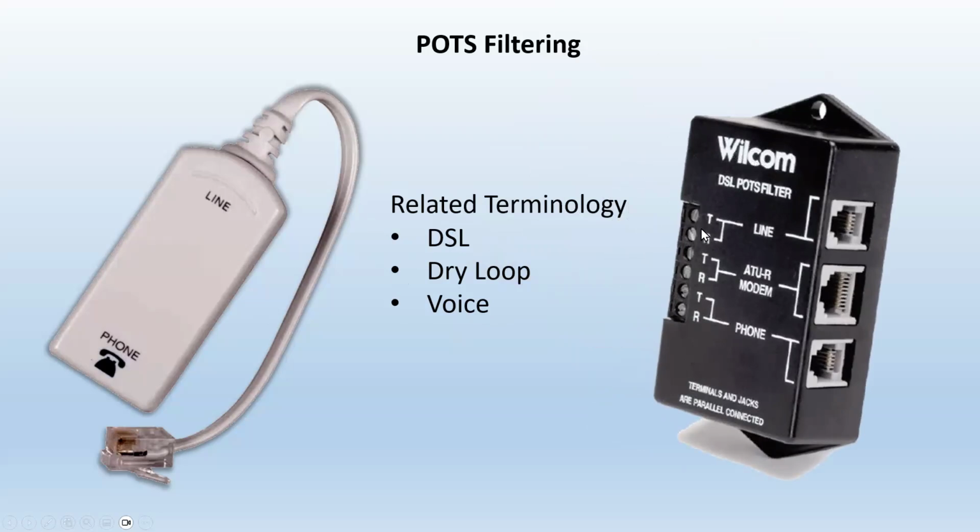Or you can connect this filter at the beginning, at the point of entry to the house. So you can connect the telephone line to either the jack or the screw terminals. If you don't have the jack, you can just connect the wires straight into that. You can choose either or, they're interconnected. So that's where the line comes in.